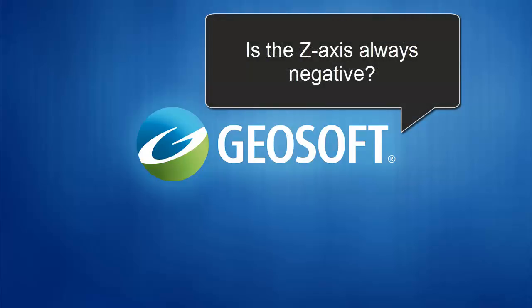In Target, subsurface data is always assumed to be Z negative down. In your Drillhole project, there's actually a parameter that you can use to flip it over. I think it's called Preferences. I can check. If you're using Target for ArcGIS and you look in the Target Project menu under Preferences, there are some options for dealing with up and down in there, but we usually assume that Z is negative down.